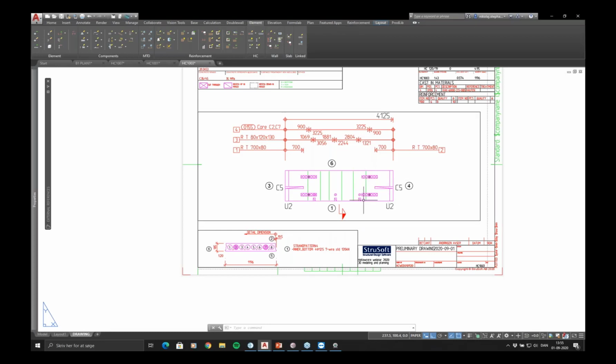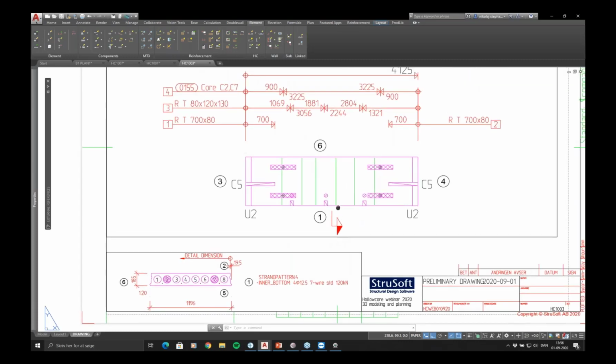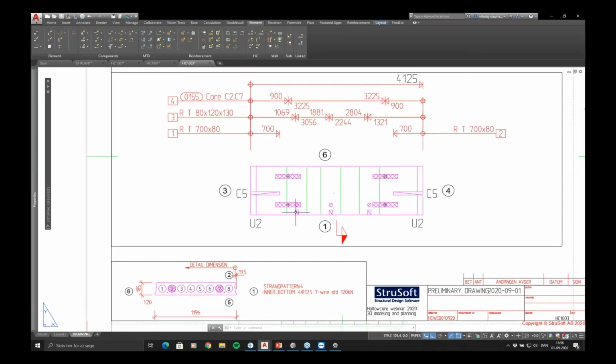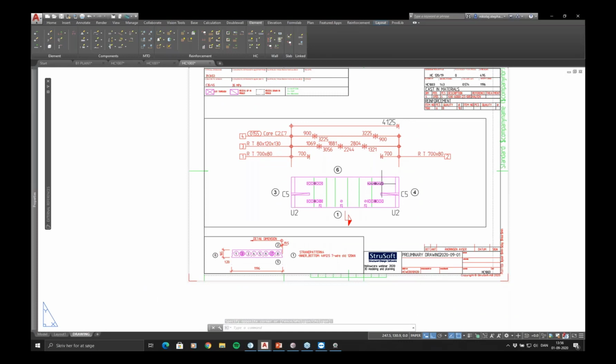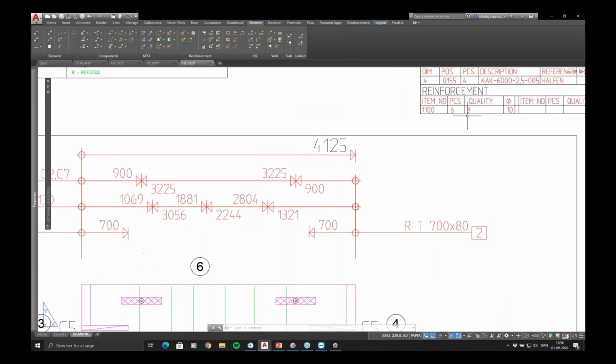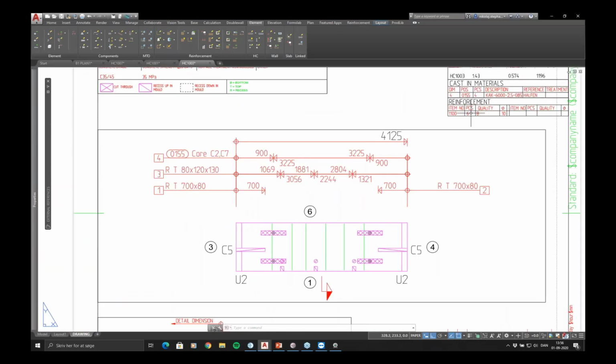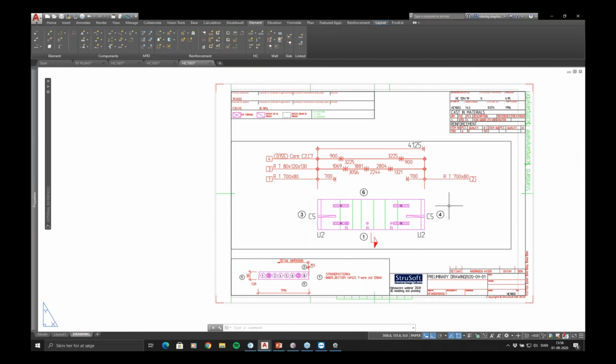So in this case, we have core fillings, we have lifters in, we have the corner or the side indents here. And there's also been set up a rule that if we have these side indents, we need reinforcement bars across the Hollowcore. So it's added reinforcement bars across the Hollowcore in a certain length and quality. And of course, we're going to list how many of them there are as well.